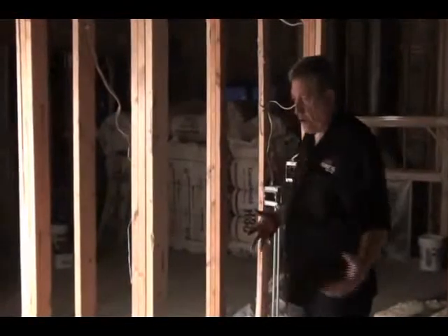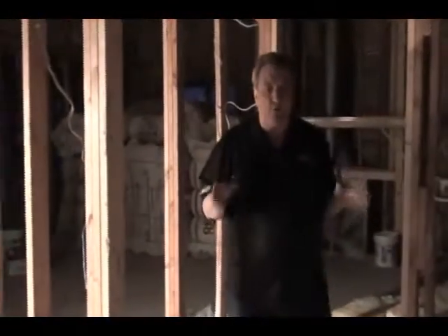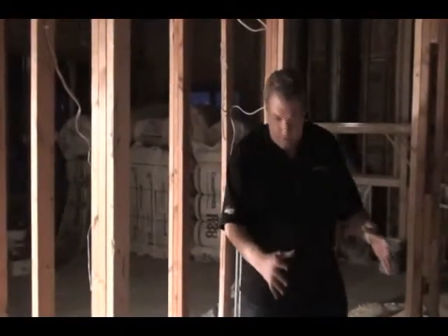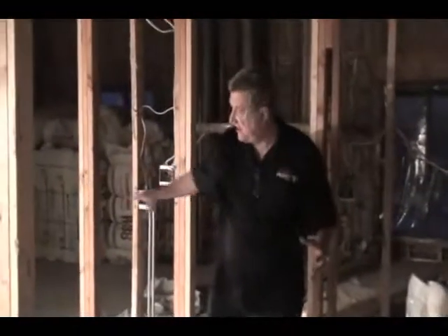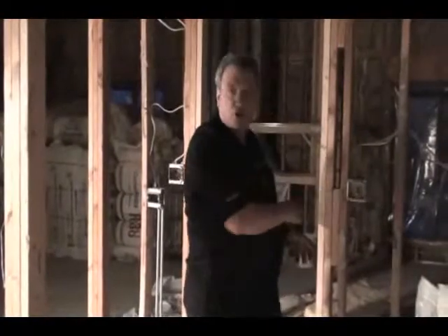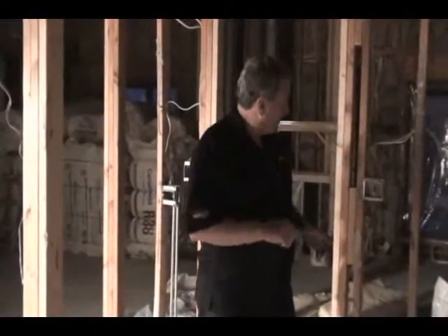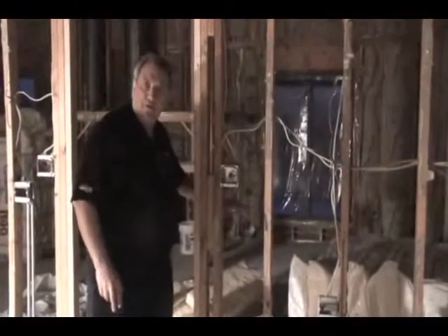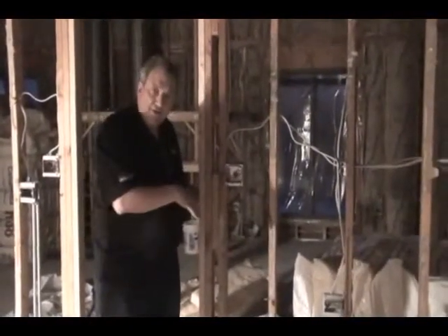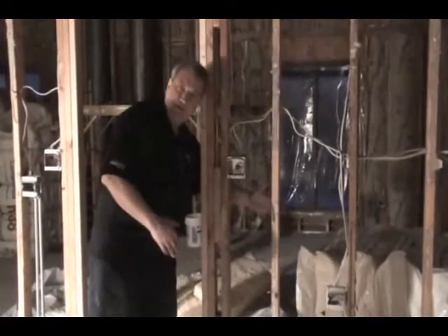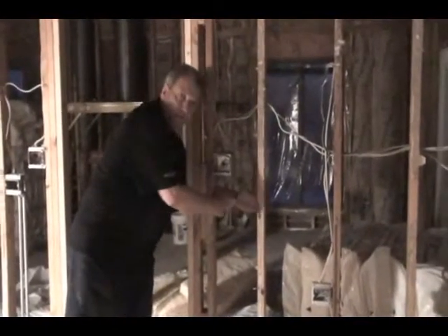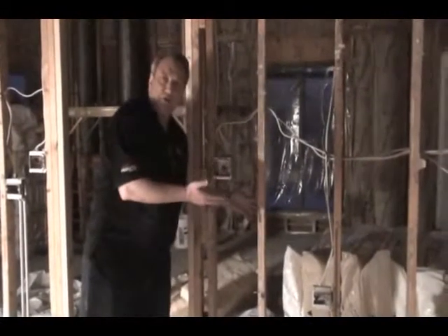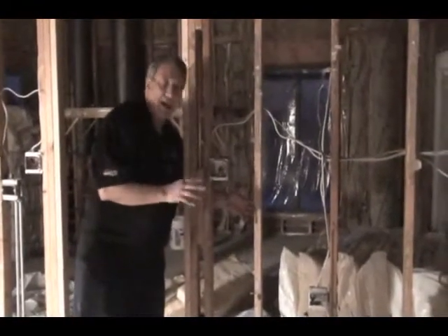Okay, so I look around, and one of the biggest key things we want to know is where to put the laser. Now in this case here, I would probably want to put it in this area here so I can see everything that I have to shoot. Let's suppose though that the customer on the other side of this wall here wanted to put a little shelf. Rather than moving the laser, we could actually put a piece of masking tape across these studs and hit points here and have a scribe line for that shelf on the other side. It's not what we're doing in this case, but just an option to show you what you can do.